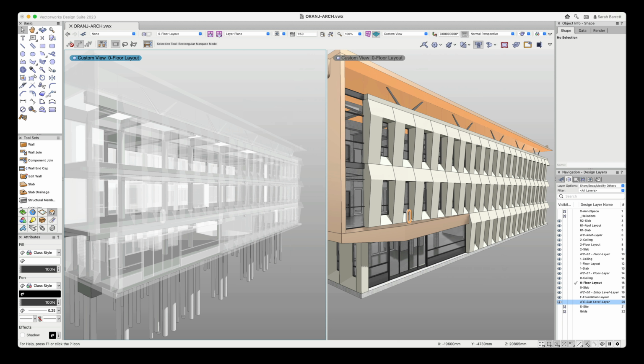The IFC models become valuable design tools for each of you. Either you or the structural engineer can tour the model in coordination meetings, either in Vectorworks or Revit. You can discuss the design and manage issues as they become apparent. I'd call this scenario manual coordination, and I think it's a great first step and a reasonable expectation when just getting started with BIM collaboration using multiple software. There are more automated methods of coordination, and Luke will discuss those in the next scenario.